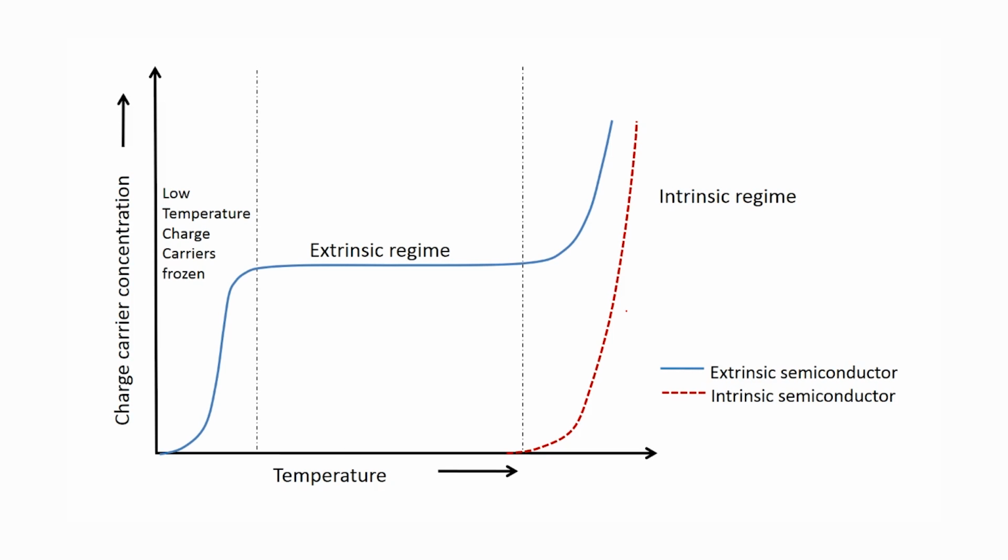Okay. So, what happens when you look at these intrinsic and extrinsic semiconductors, just to give you an idea of how they behave differently. When you take both these semiconductors and look at the charge carrier concentration, which is what is marked on your y axis here, as a function of temperature: at very close to 0 Kelvin, all the charges are held within their base energy level, their lowest energy level, which could be the filled valence band, or the acceptor level or the donor level. It just sits there. I mean, nothing moves. It is basically just sitting at those values.